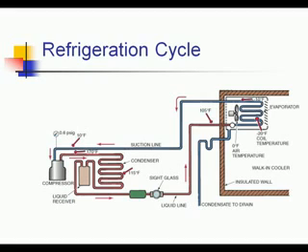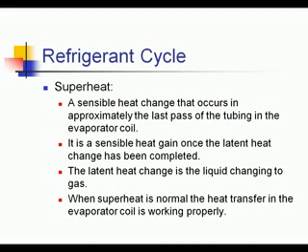So again, natural heat flow. It comes from the cooler into the evaporator. When the refrigerant is 100% vapor, a sensible heat change occurs that will further heat the vapor. This is superheat. Once the vapor is formed, superheat increases the temperature. The refrigerant returns to the compressor through the suction line. So the refrigeration cycle is once again complete.